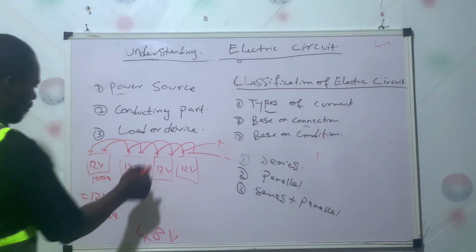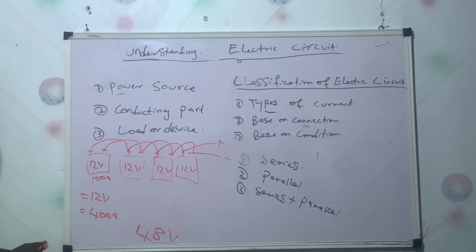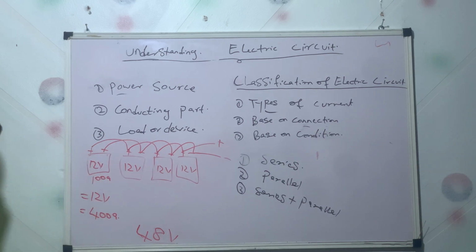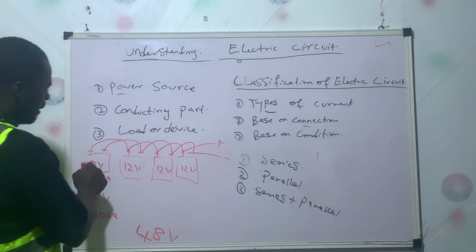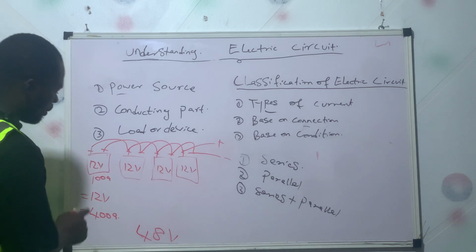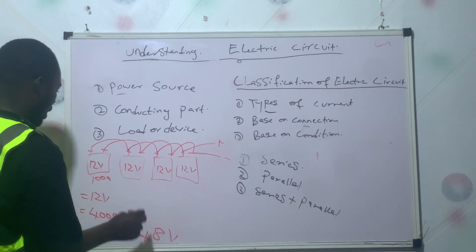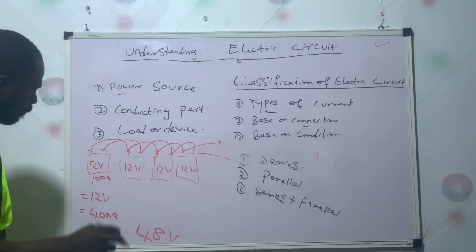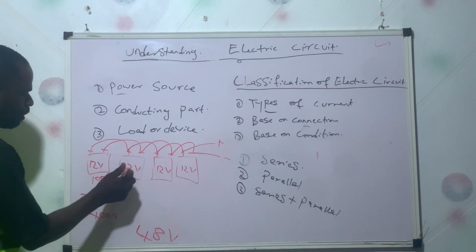That is why the only type of inverter that can work with this kind of connection is a 12 volts rated inverter. The 12 volts rated inverter is your best choice for this kind of connection. For this capacity of battery bank, a 12 volts inverter is not your best choice, compared to a 48 volt system connected with this same battery. Your 12 volts inverter will run down.